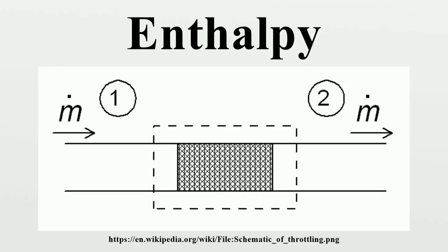If we choose the shape of the control volume such that all flow in or out occurs perpendicular to its surface, then the flow of matter into the system performs work as if it were a piston of fluid pushing mass into the system, and the system performs work on the flow of matter out as if it were driving a piston of fluid. There are then two types of work performed: flow work described above, which is performed on the fluid, and shaft work, which may be performed on some mechanical device. These two types of work are expressed in the equation. Substitution into the equation above for the control volume CV yields: